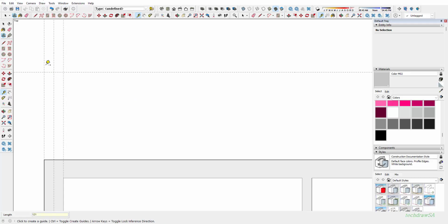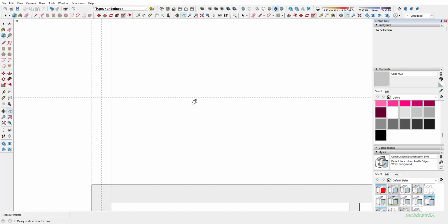So that's the middle, and now we know that the default size of our foundation is going to be 600 by 200, and because we know that our question says 600 by 200, we know that's the default, but please always double check if they have not overwritten the default and that they have maybe made the foundation a different size. So you always stick with the size that's given on your exam paper.